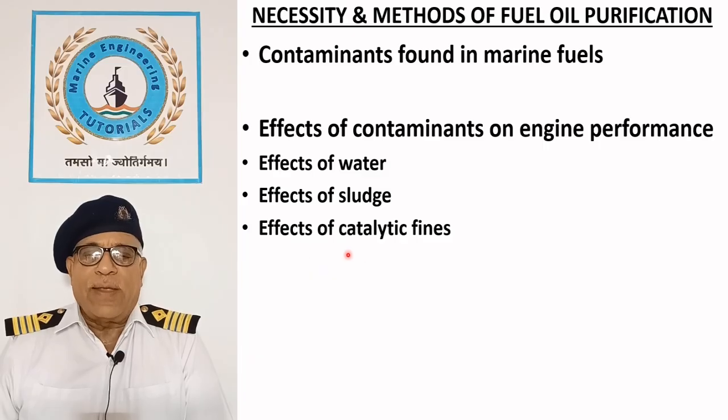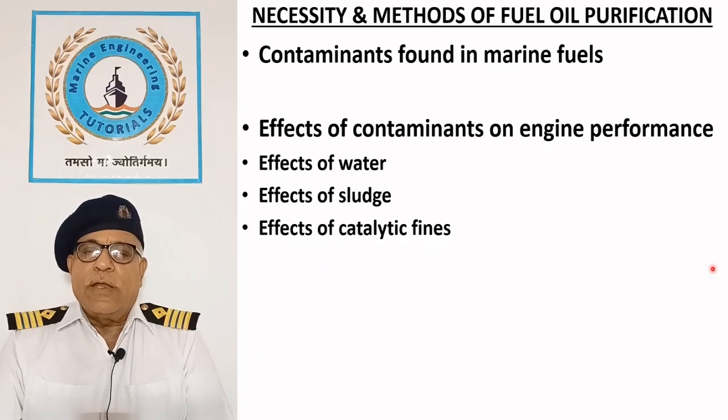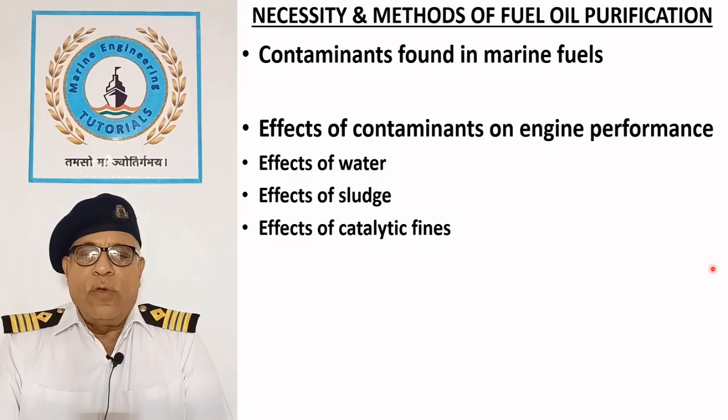Effects of catalytic fines. Catalytic fines consist of aluminum and silicon, which enter the fuel during the refining process and are highly abrasive. They cause severe wear on fuel injection equipment, piston rings, and cylinder liners. They can lead to scuffing and liner seizures and can be removed only by purification.